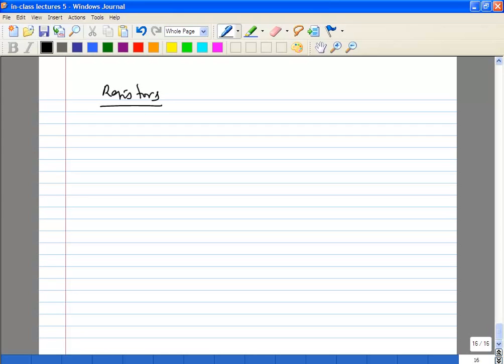So you have 5 or 6 different kinds of resistors. Many of them are based on silicon itself. So you have N type, you have P type, you have different kinds. There is something called a silicided resistor. Silicided is basically you have a polysilicon piece, and then you add some metal deposition over that to reduce the resistance. The metal forms a silicide compound with the silicon, and that reduces the resistance.